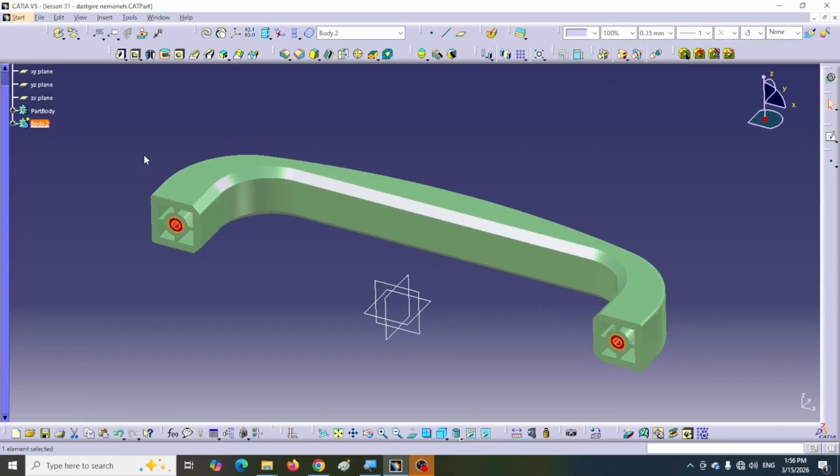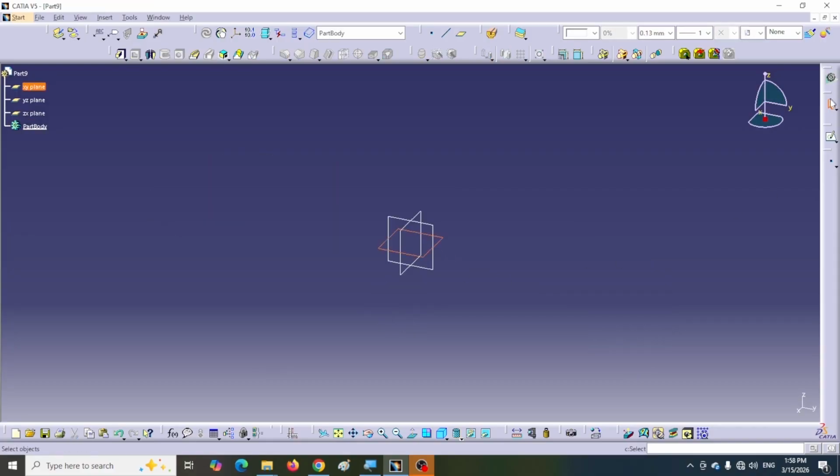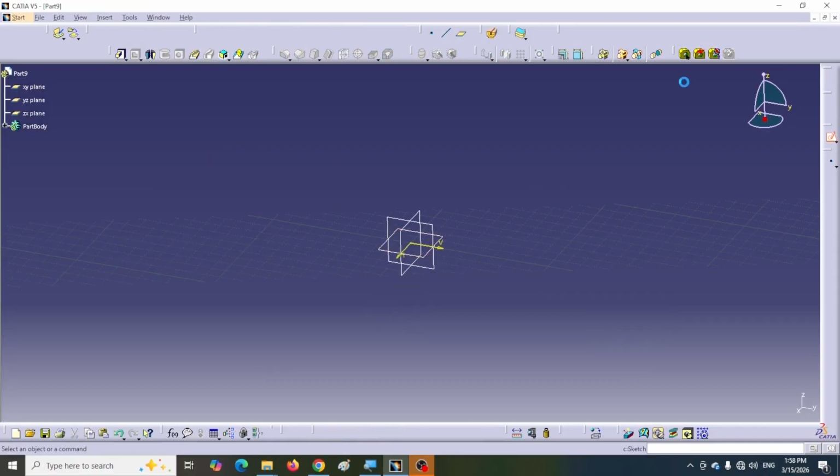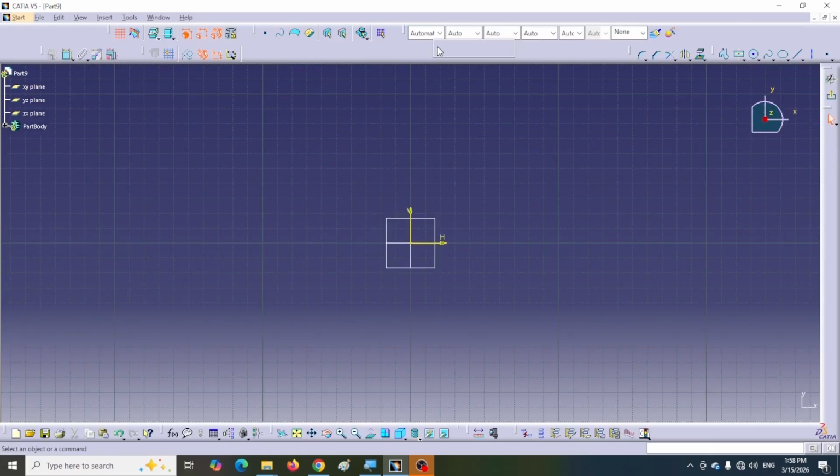The main use of multi-body can be divided into three groups: step-by-step design, mold design, and insert design before assembly. Remember that we can copy a body and save it in another part. But the part you copy must not depend on another body. Otherwise, only the final solid can be transferred without the full design tree. First, I create a part with two bodies. Notice that I do not use Boolean tools.